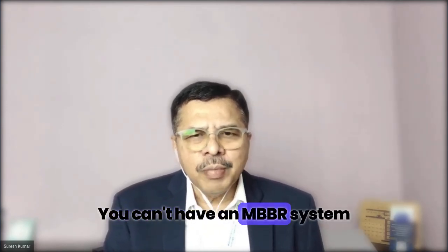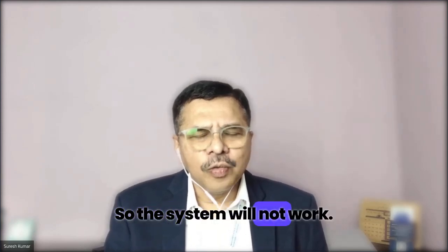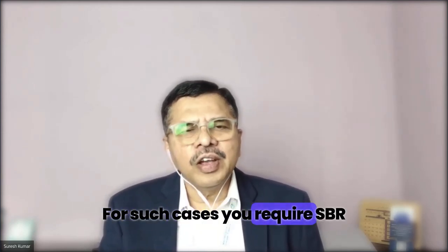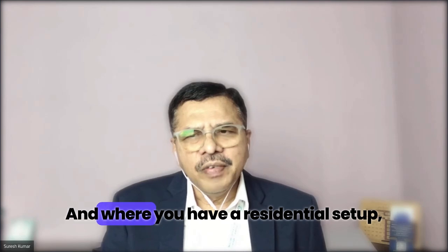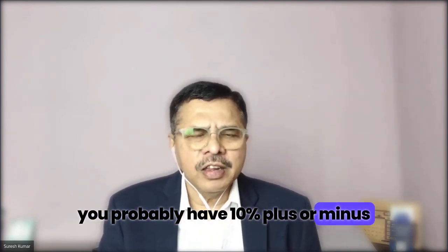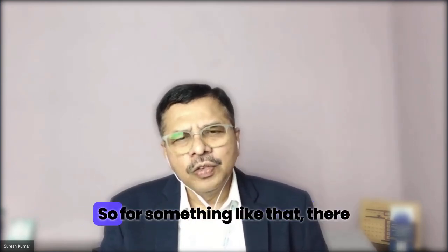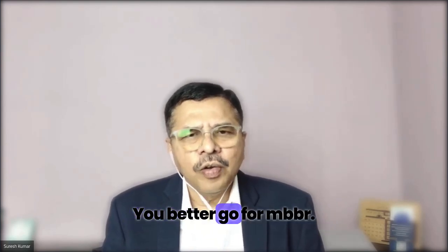You can't have an MBBR system where one day you give 100 KL, next day you give 50 KL. So the system will not work. For such cases, you require SBR, sequencing batch reactor. All right. And where you have a residential setup, you probably have 10% plus or minus depending on the number of users. So for something like that, there is no point in going for SBR. You better go for MBBR.